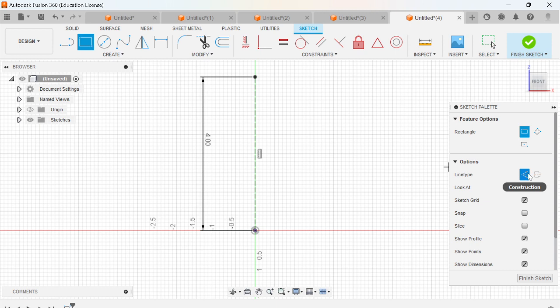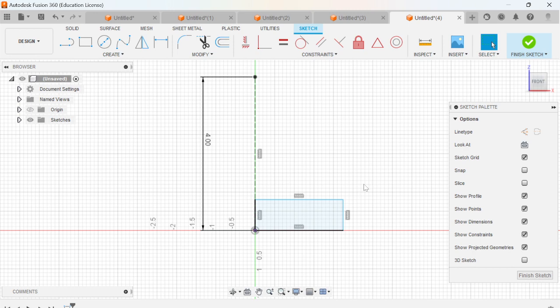You can make a circle with construction geometry, and whenever you go to revolve it, it won't let you. Fusion doesn't see it as a closed body. Only the typical straight solid lines count as bodies. So we're going to change it off from construction because now we're making stuff that we want to make into matter. We are going to make a bottom part for this chest piece. We'll dimension this 0.75, and we will give this a length of, we'll say, 2.